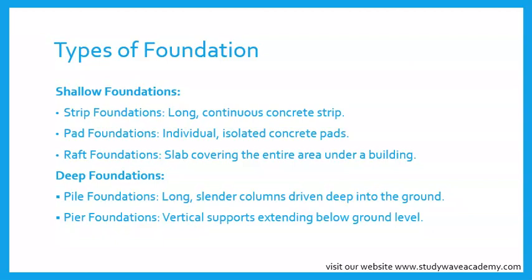The shape of the raft foundation is like a big flat slab under the whole building. Spreads the weight evenly over a large area, okay? Do we understand? So these shallow foundations help keep the building steady without going too deep into the ground. Okay?